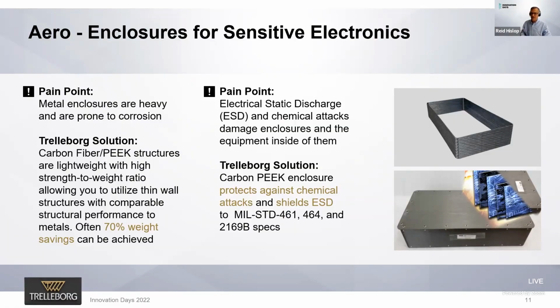Being a thermoplastic, the enclosures are resistant to chemicals and fluids and are also recyclable, unlike other thermoset competitors. But using our automated fiber process, there's flexibility in the geometry, as you can see here by the photos I've included, as well as allowing scalable manufacturing for large quantities. Again, there's no post-cure process with these because they're thermoplastics, they're cured on the fly. And we'll discuss that in a couple of examples coming up.